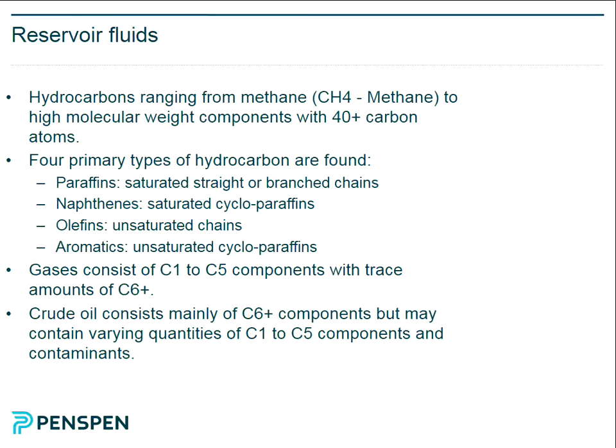Now, if that solid forms as particles in the water, then it will just be transported out of the reservoir or out of the pipeline. That is not really a problem. But sometimes they form solid scale on the inside of the pipeline, which can completely block the flow. So scaling is a potential problem with salts in water.